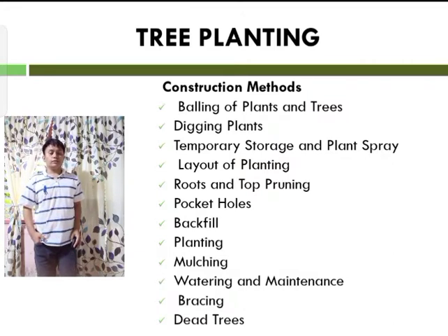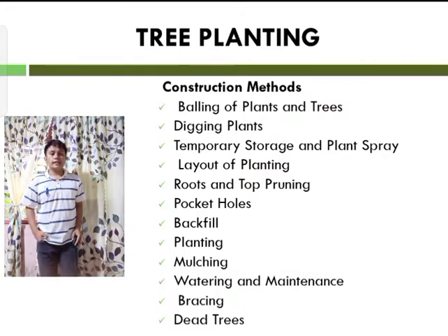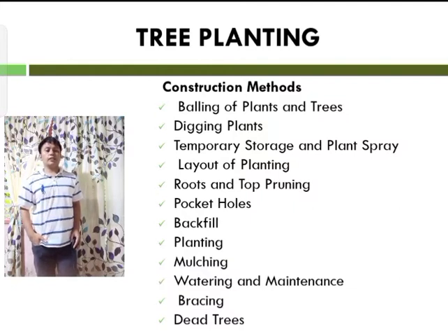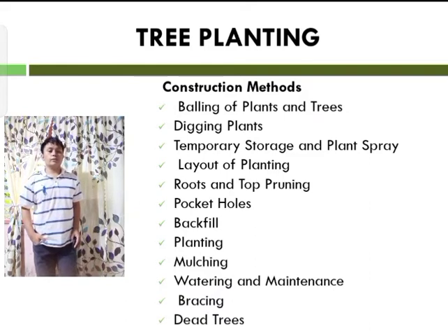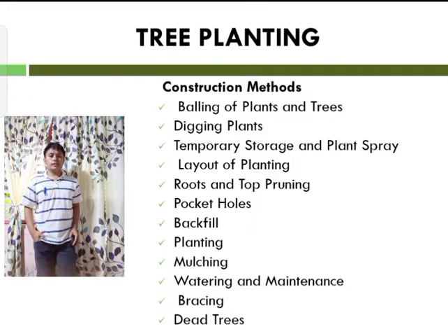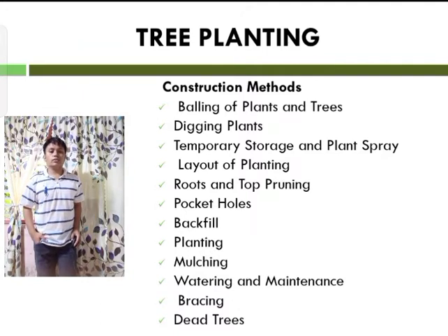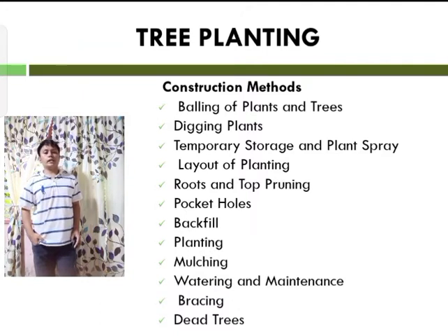So next is the tree planting along National Road. The trees to be used for this purpose shall be of varieties whose root systems grow downward rather than sideward, to avoid situations where the roots spread sideward and consequently destroy the road and sidewalk slabs.